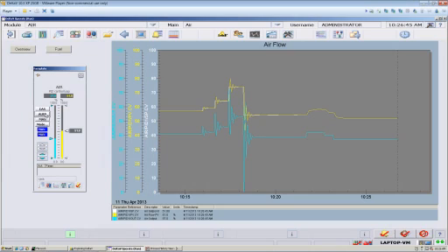Now if we put this loop in automatic mode, if I make a set point change, I told you I chose a Lambda time of 12 seconds. My time to the new steady state should be 4 times that, or 48 seconds. Let's see how predictable we are. First of all, we should get to that set point in a smooth fashion. It should look like that same first order self-regulating kind of shape. There shouldn't be any overshoot, and I predict that I'm going to get to set point in 48 seconds.